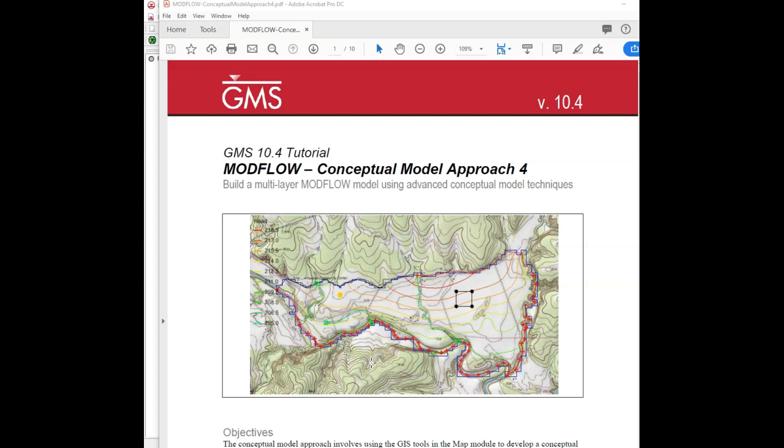Hey everybody, in this video we are going to do the fourth and final exercise related to our East Texas model. And in this case we're going to do a number of things to our model. We are going to import a polygon representing the outline of this landfill, and then we're going to adjust the recharge in that part of the landfill so that later when this model is used for particle tracking and contaminant transport analysis, it has the right flow conditions based on the amount of leachate coming out of that landfill.